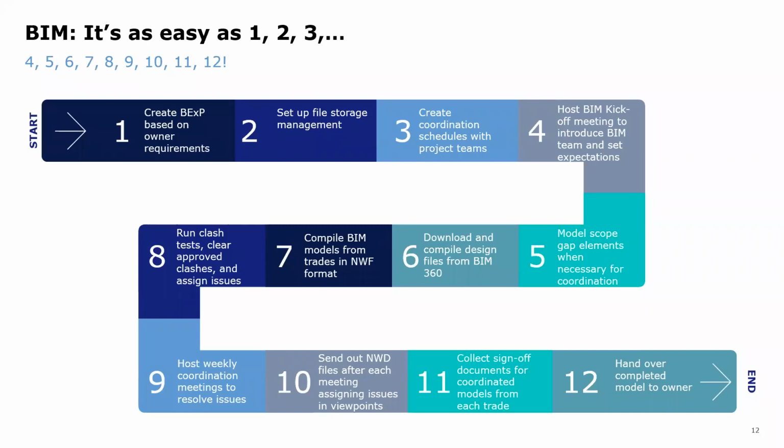From there, we'll compile all the design files and the subcontractors' files, put them into Navisworks, run clash tests, host coordination meetings, and send out NWDs with issue assignments and get them resolved. And then sometime down the road, we'll collect all the sign-off documents and hand over a completed model to our owner.